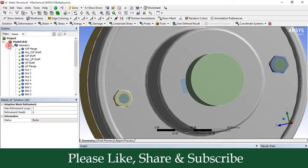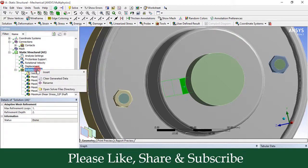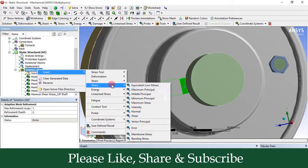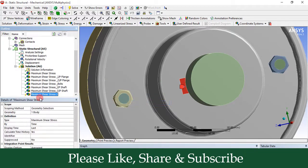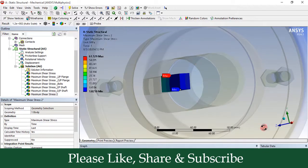Now select the body button, select this key and left click on this solution, right click on it, go to the insert, go to the stress, go to the maximum shear stress, and you can see here it is turned into red color. So we have selected the output key for maximum shear stress parameter, right click on this maximum shear stress parameter and select the option evaluate all results.